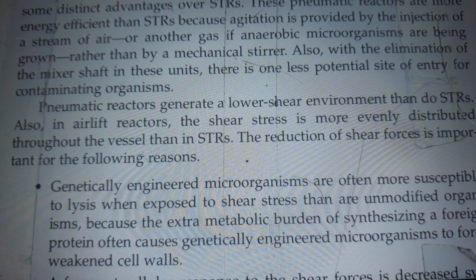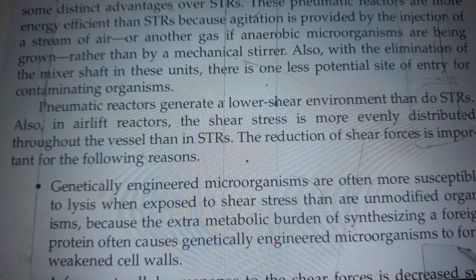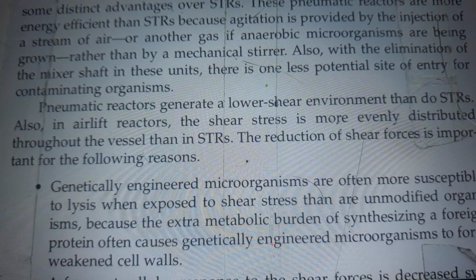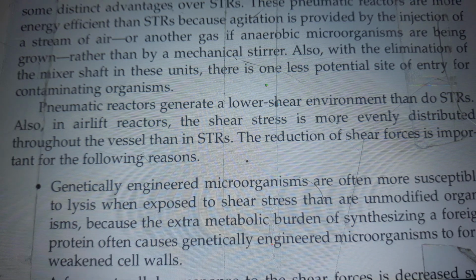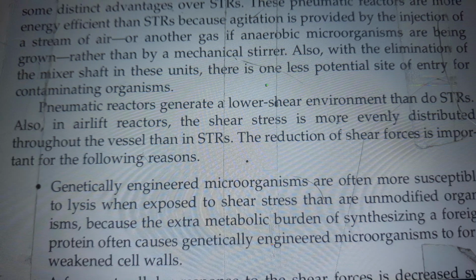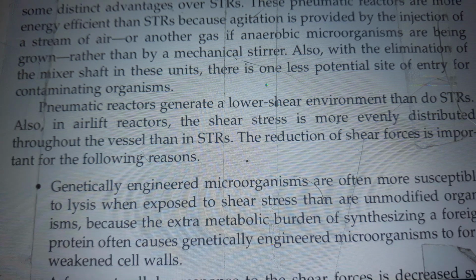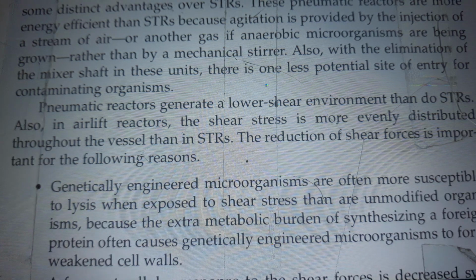Also, with the elimination of the mixer shaft in these units, there is one less potential site of entry for contaminating organisms. Pneumatic reactors generate a lower shear environment than do STRs. Also, in airlift reactors, the shear stress is more evenly distributed throughout the vessel than in STRs. The reduction of shear forces is important for the following reasons.